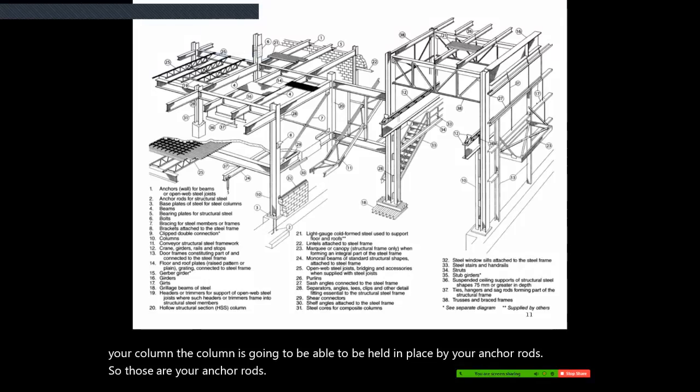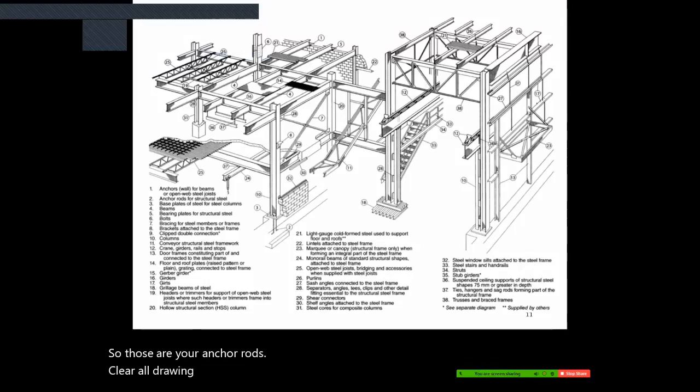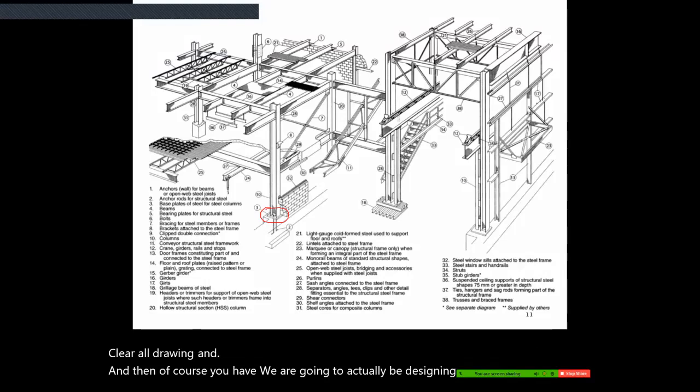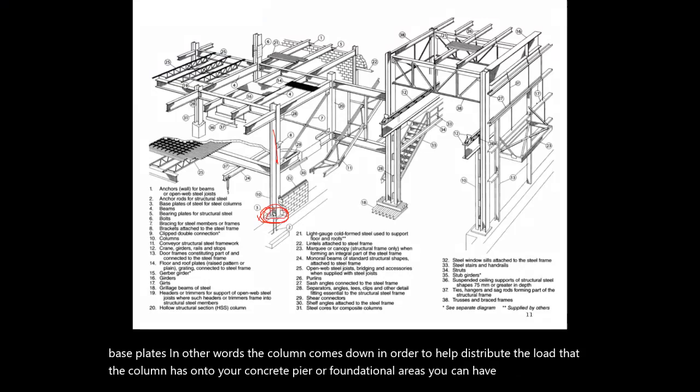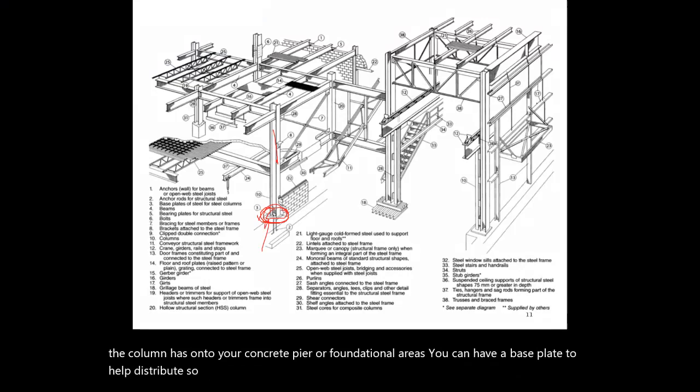Clear all drawing, and then of course we are going to actually be designing these things. These are base plates. In other words, the column comes down, and in order to help distribute the load that the column has onto your concrete pier or foundation, whatever it is, you can have a base plate to help distribute. So we are actually going to be designing these base plates in this course.